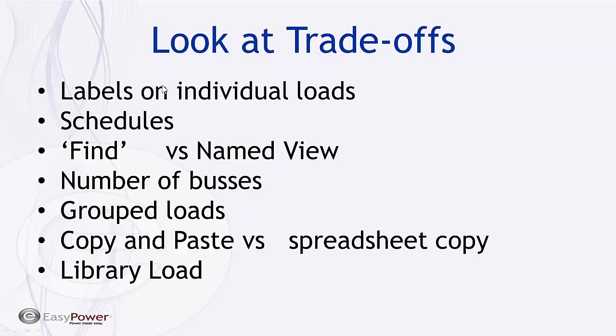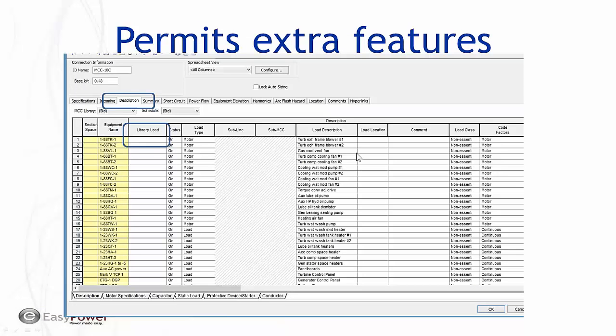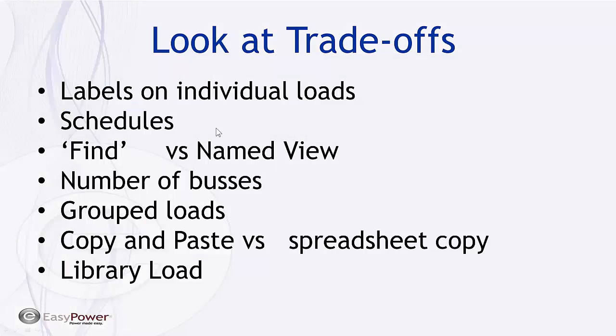And so as with panels, the labeling scheme is taken down to the main bus on the MCC, and consequently the loads would only make a difference in so far as their contribution to the total current, but we would not have an individual label on every load.